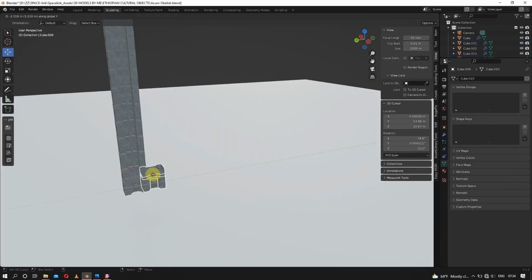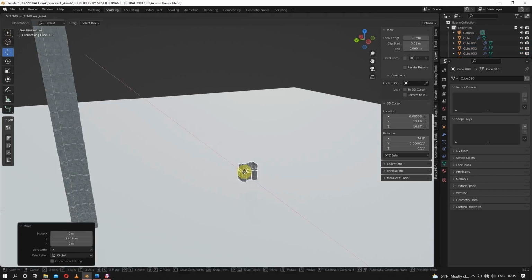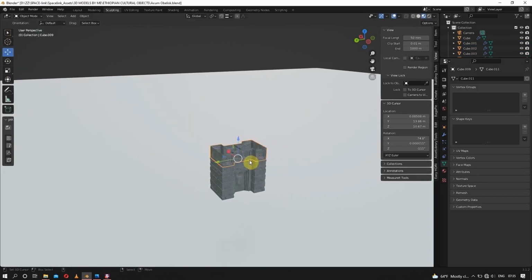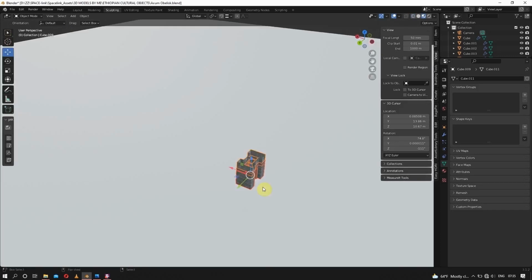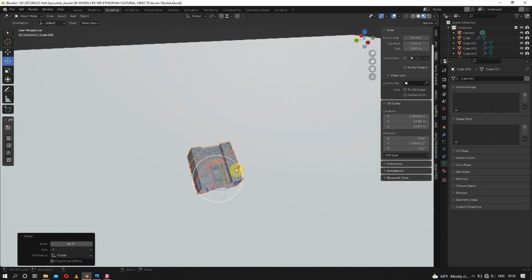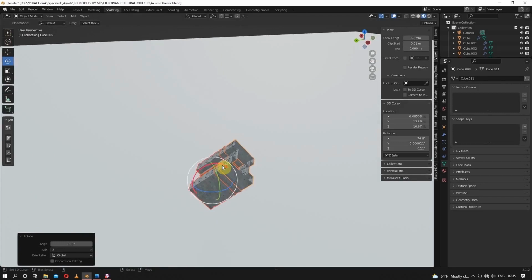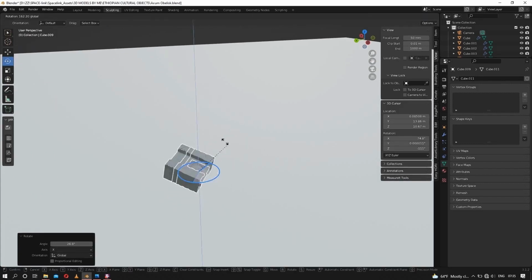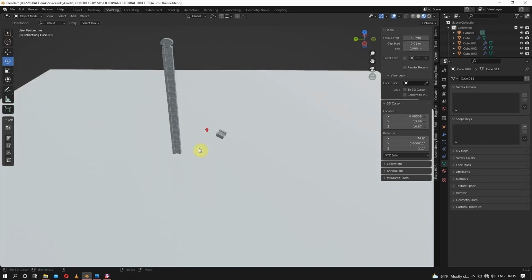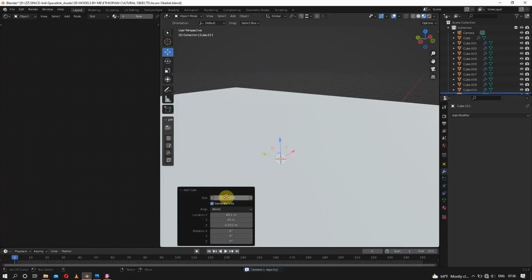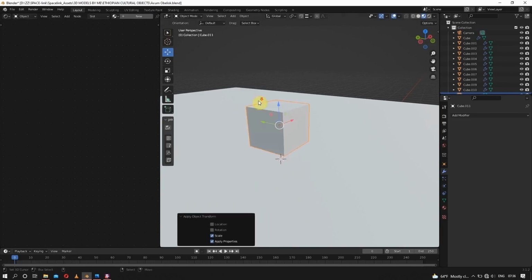Let's copy some segments of the statue and put it somewhere on the ground to make it look like some are somehow falling down on the ground. Rotate it whichever way you want. So the trick is to not make the open surface seen from the camera angle.